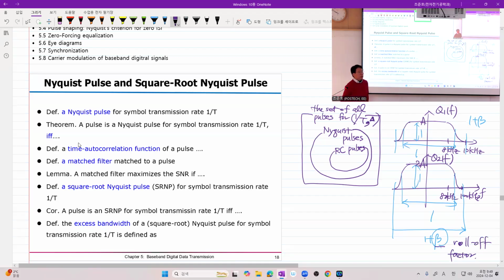In general, for Nyquist pulses, you may further divide like this: band limited, band unlimited. For band limited pulses, you may have beta changing from -1 to an arbitrarily large number.